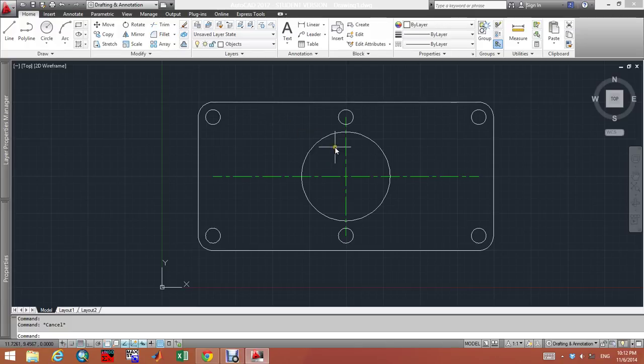So that's going to be really a mess. So you need to make sure every time you change your current layer, you need to hit escape to deselect everything, unless you really want to do that and intentionally want to bring some components to the other layer.